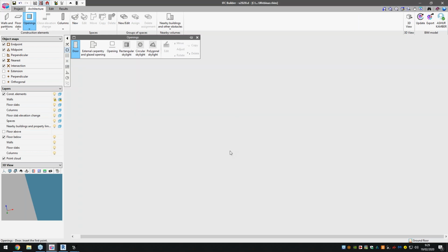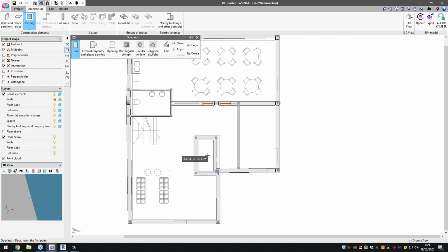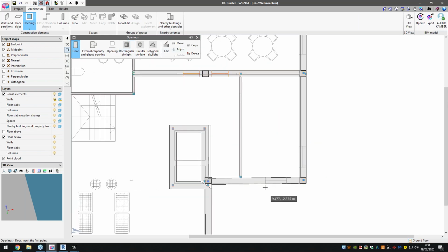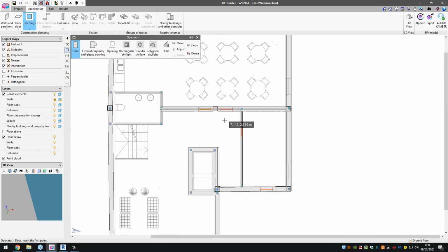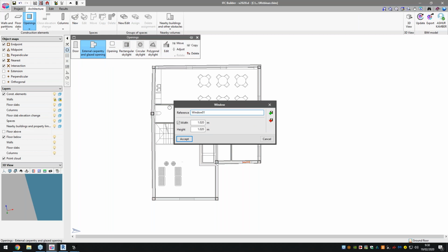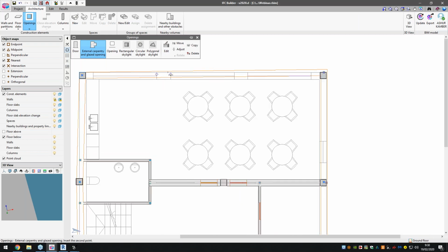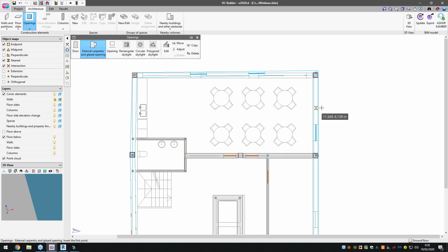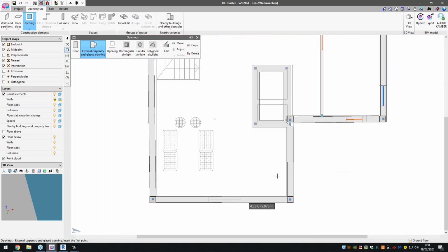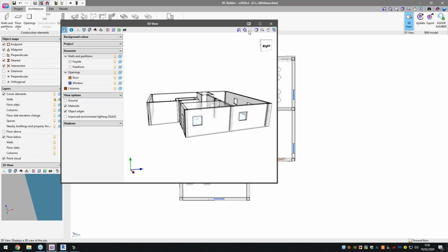Let's leave it as a standard door, and I can come over here to the project and create the door. The door is there. And of course, I'm not sticking to the template, but I'm just trying to demonstrate the overall workflow. Glazed carpentry and openings. And you can see here in little to no time, I'm able to create a very simple architectural model.